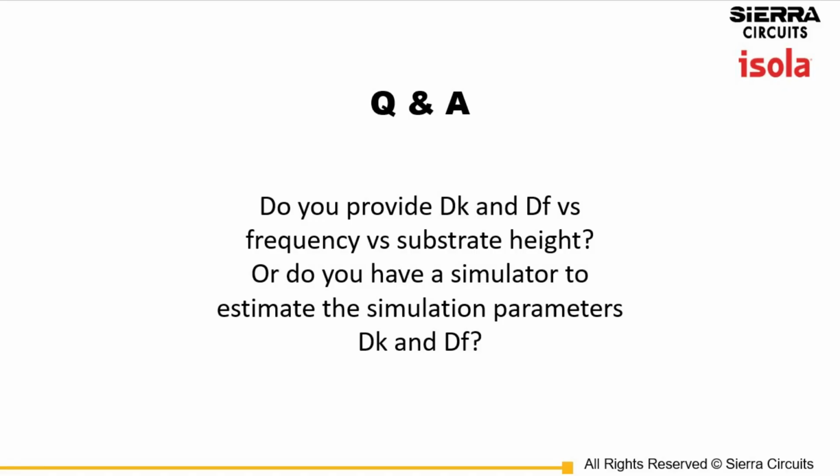Thank you, and you can see the question below. I think this is part 2. Or do you have a simulator to estimate the simulation parameters? Yeah, that's something we do in some cases. There is not really a way to measure every thickness, every construction. That's just from the test methods themselves. They are not conducive to any thickness, but you need certain thicknesses. So you need to do some, let's call it extrapolation, or if you want to use a more fancy word, simulation. You basically look at how things change for a particular construction, and then you derive what you expect for other constructions. So yes, I would rather call it extrapolation than a simulation, but yes.